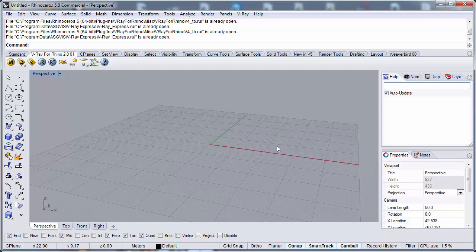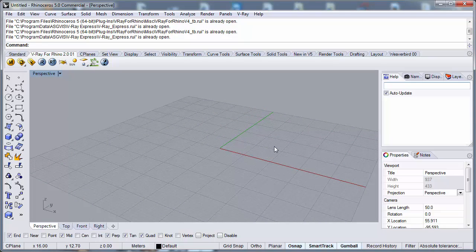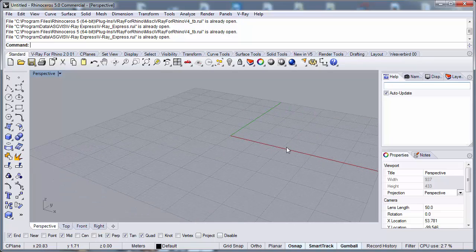And another subject I'd like to mention briefly now is that Rhino has many import and export options. If you're coming from AutoCAD, you can get your DWGs in. They import very nicely. You can get 3ds, you can get curves from Adobe Illustrator, etc. And you can also export in many formats like OBJ, DWG, 3ds. And I think in newer versions of AutoCAD you can directly import the 3DM file. So check this out also.